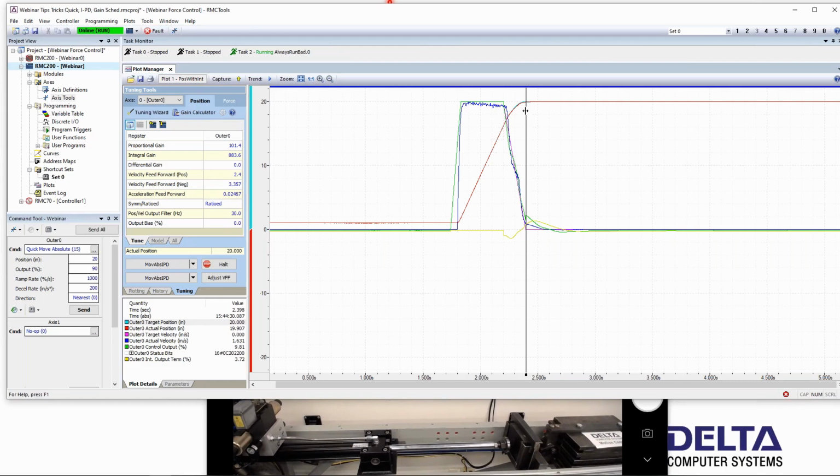A few classic things are setting the valve far away from the cylinder, because now there's a time delay in the oil pressure wave going from the valve to the cylinder. You know, there's the speed of sound in oil and the speed of sound in air. It's only going to happen so fast. Also, hoses kind of can take things up.